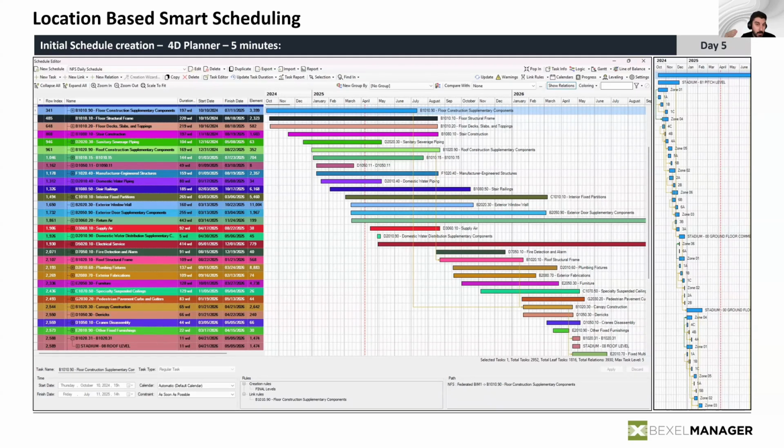And then the algorithm, again, based on these inputs from the professionals, simply adjusted durations in this schedule to fit these limitations. So, okay, if I could execute 500 cubic meters of concrete per day, and if I have a slab that is 1,500 cubic meters large, then the system will automatically say that we need 3 days completely to pour this